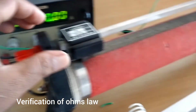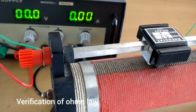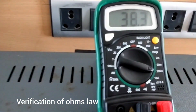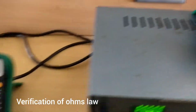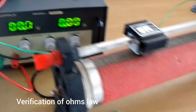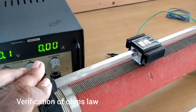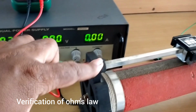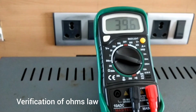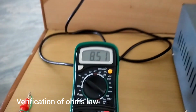Now move the rheostat to some extent. It gets moved from maximum position to minimum position. Now we can note down the ammeter reading and voltmeter reading. Now move the rheostat again to minimum position. You can see the ammeter reads 39.5 milliamps and voltage is 8.50.